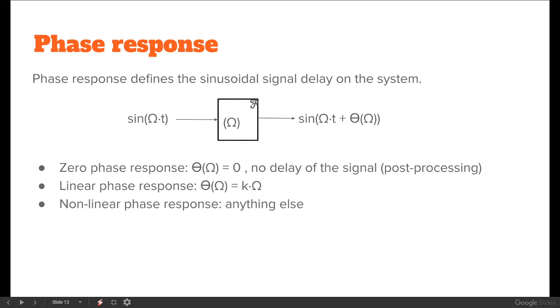So the constant time shift is very important, for example, in data transmission, or if you are filtering data which has pulses. If the phase response is not linear, then the pulse shape starts to skew. Time delay.